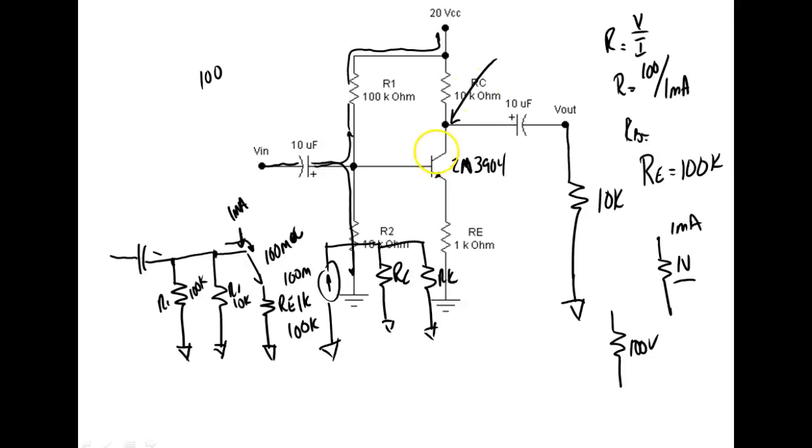So this resistance right here would be equal to 5K ohm if I load it. Do you understand? Yes or no? So what would the gain of this circuit be? Well, instead of being a gain of 10, it's going to be a gain of 5. We still do it the same way, but the voltage gain formula for this is actually A. So we use A to represent what? Gain. We've already talked about this, right? Okay. And voltage gain would be equal to R out